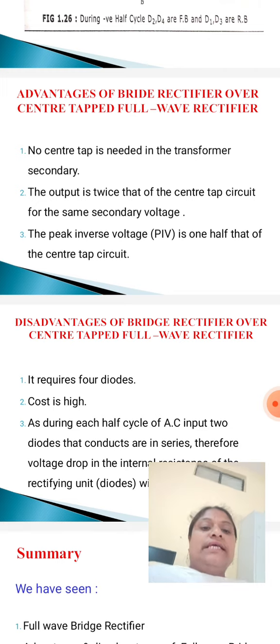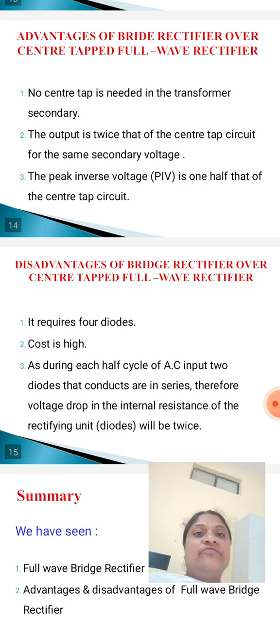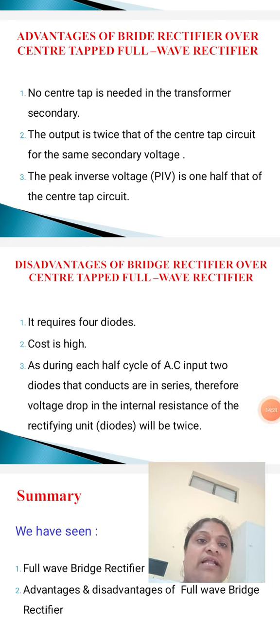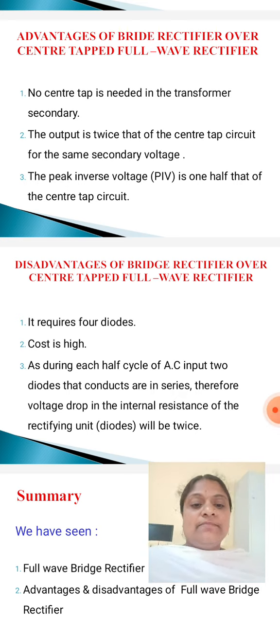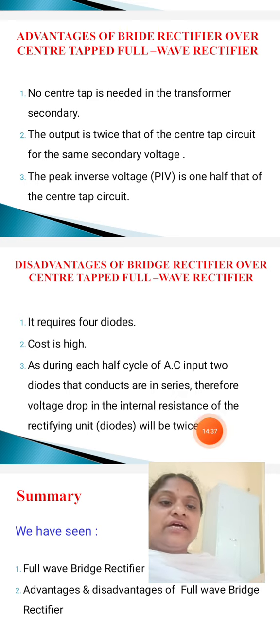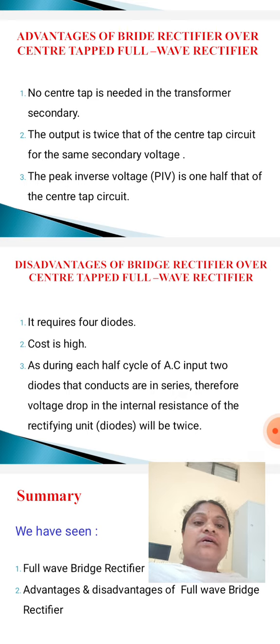And next, the third advantage of bridge rectifier over center tapped full wave rectifier is the peak inverse voltage is 1/2 that of the center tap circuit. These three are the advantages of bridge rectifier over center tapped full wave rectifier.